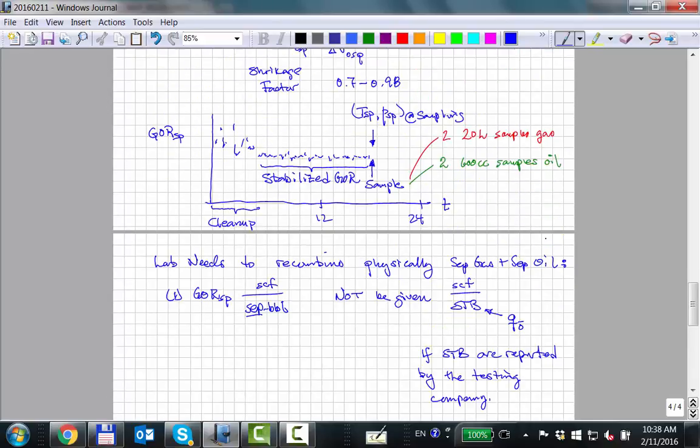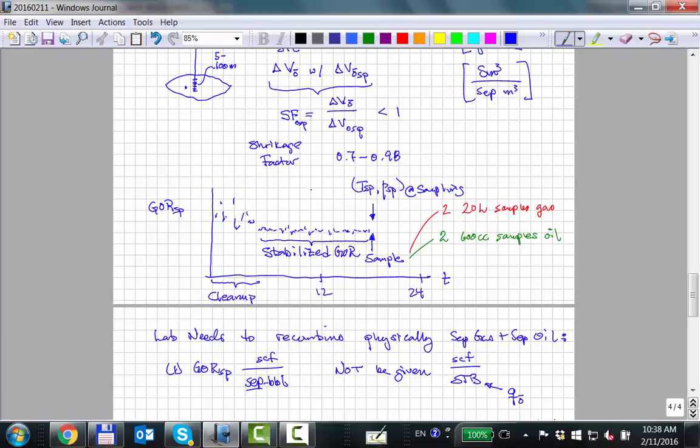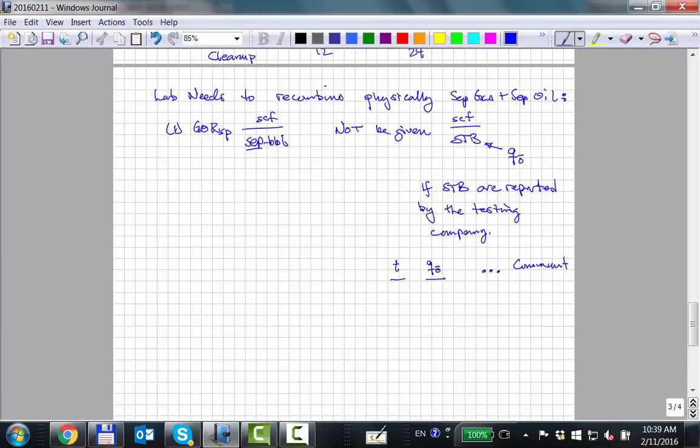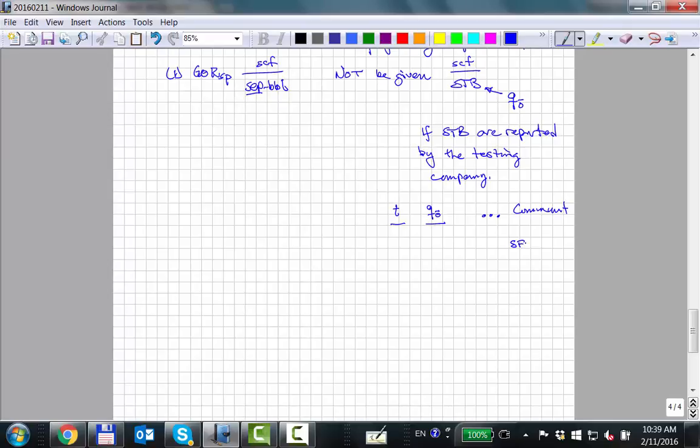And when the guy or she went to the bathroom and did this periodic shrinkage factor calculation, they will put over here as a comment: shrinkage factor 0.826, maybe 0.83, okay? And then 3, 8, 12, 15 hours later, they'll put another one, 0.712. Probably the separator pressure went much higher for some reason. And then maybe later they might have a shrinkage factor, what they report as 0.86, okay?